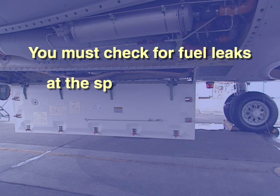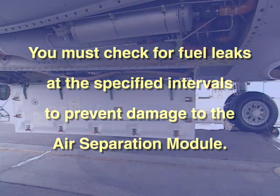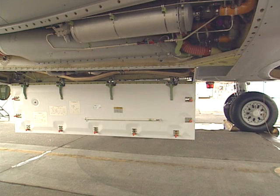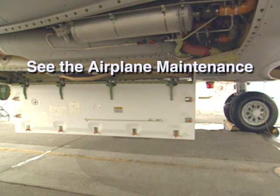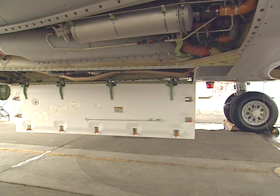The air separation module can be damaged by fuel, so you must check for evidence of fuel leakage at the specified intervals. The example we'll see uses one of the drain valve configurations. The process is similar for airplanes with the drain cap near the backflow check valve. See the airplane maintenance manual for more information.